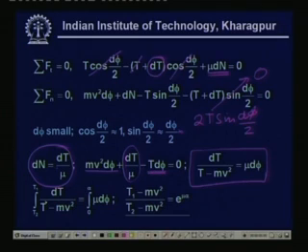So, that comes out to be dt by t minus m v square, and you have seen in this particular pulley what we have drawn earlier, this comes out to be the angle of wrap, that is alpha we are considering. So, we consider from 0 to alpha the entire length from where T2 to T1 has occurred. So, this is 0 to alpha mu d phi.